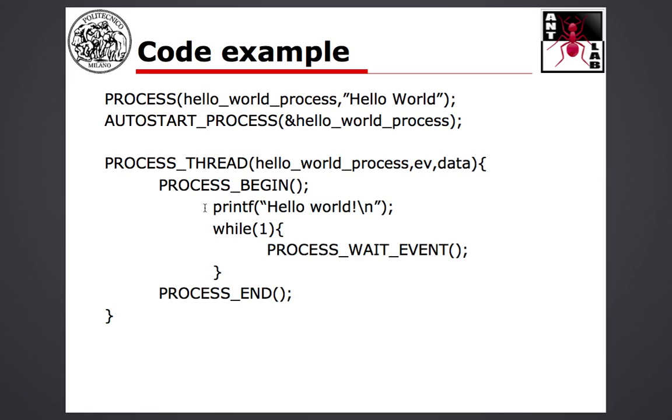if you think about updating this code on top of a mote, it does nothing basically, because motes have no terminal, they cannot print anything. They are typically deployed somewhere, they have wireless communication, but they cannot print. Now, this printf in Contiki is basically for using it with Cooja. So when you print something in Contiki and you run the simulation in Cooja, you will see the proper string which is output in the terminal of Cooja.